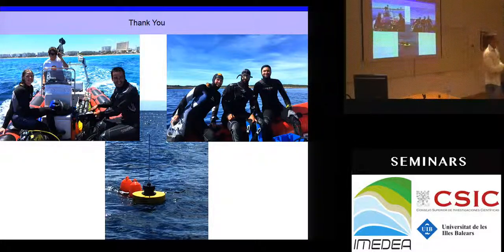I have 2 questions. The first one is just a clarification. So you introduced the vegetation as a non-linear dissipation in the wave equations. Is that correct? So you just put a force which is proportional to the square of the velocity of the waves. Is that correct? Yeah, that's the force, and then the work done by the force leads to the dissipation. Exactly. So it's non-linear. There's a non-linear dissipation.